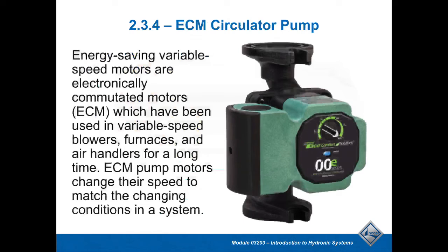A motor that previously, like a PSC motor, might have only been in the 50-60% efficiency range, we can now utilize a pump that might be closer to 75-80% efficient. Just like we've done in furnaces where we've taken a blower with an ECM motor on it. So this is a current technology that is out there that does a really nice job.